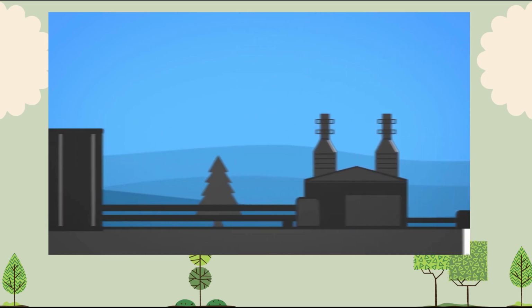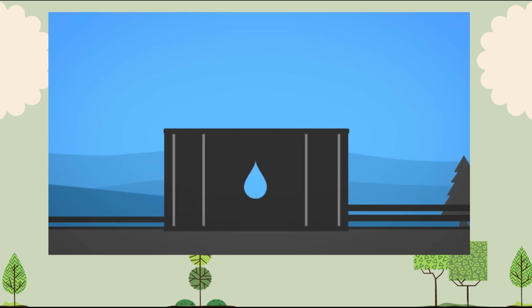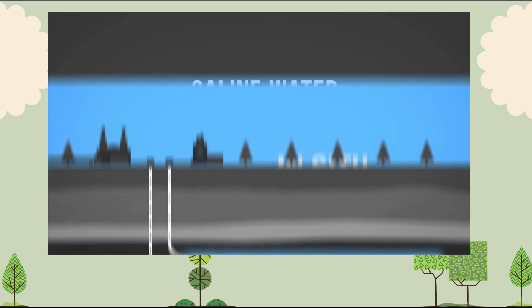In addition, water use is another important concern. The SAGD process requires a significant amount of water, though 80 to 95% of the water used is recycled back into the process. Some SAGD operations also use saline water that is determined to be unsuitable for drinking or irrigation purposes in order to minimize the use of fresh water. That's in situ.